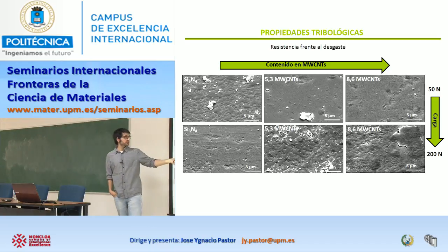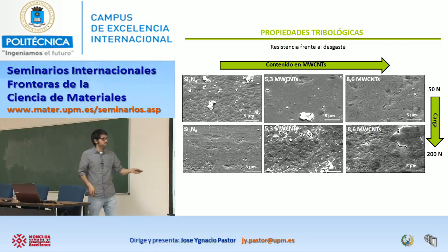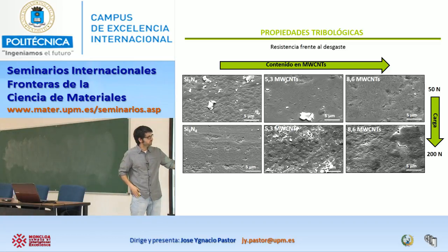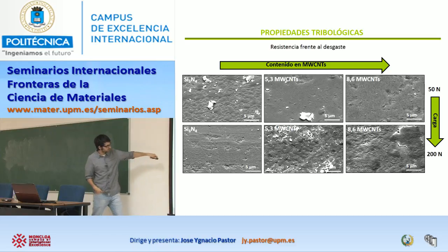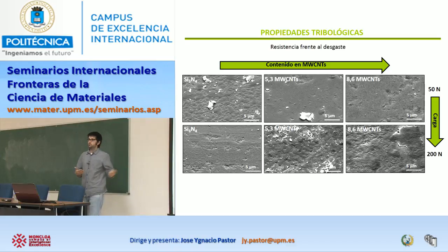Well, this crack is what I told you is a tribofilm. This is not the material. This is the compaction of the degradation of the material. It degrades, it puts itself on the surface of your material, in between the two bodies, what is called the third body, and it's lubricated. Then it's passing, and of course through the pressure, it's like attached to your material, but it's not directly your silicon nitride. It is only the debris. However, here you can even see, briefly, this slide. This is because the surface is not protected anymore. Okay.